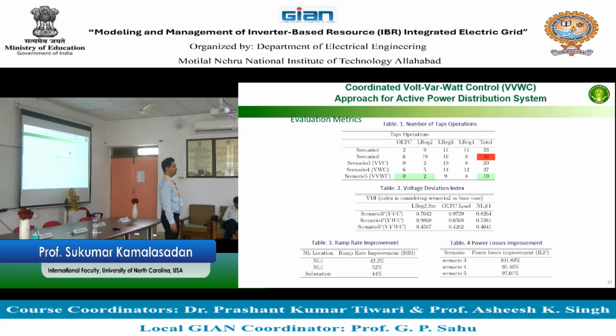So let's assume that there is a load and this load is lifted, a high load change. How fast the generator changes to support that load is important. All the generators together, if they are not changing fast to support the load, then the protective systems will activate and get rid of those generators. And if it gets rid of the generator, then you have cascading: there is more load, less generator, less generator.